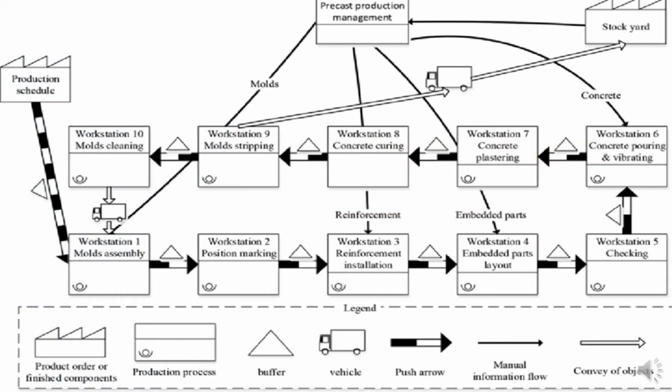Precast concrete process. A large number of concrete structures, about 6% of the building frame market, are precast. The individual components are prefabricated off-site, then taken to site where they are erected. The figures illustrate the precast concrete process. The precast factory often has specialist workshops for the manufacture and maintenance of molds, and for the production of jig-built reinforcing cages and connections.